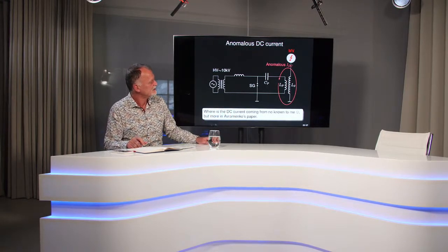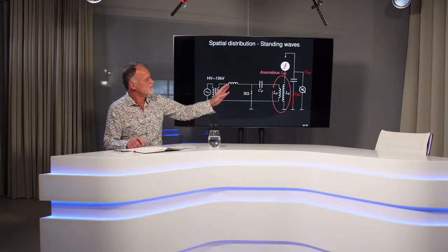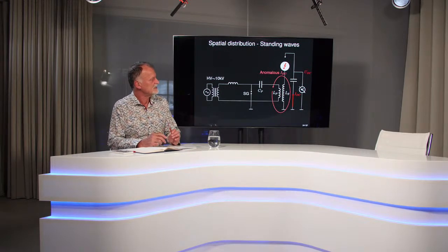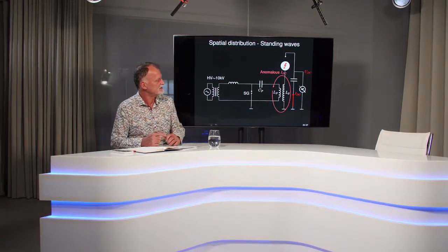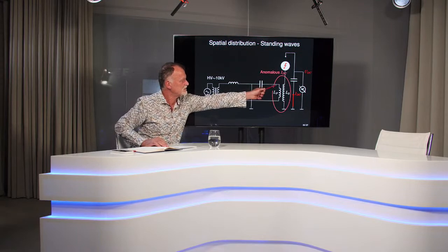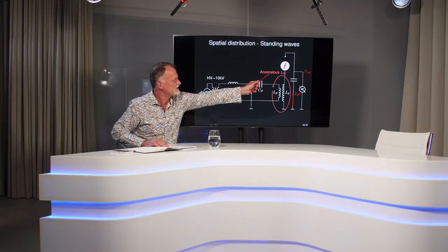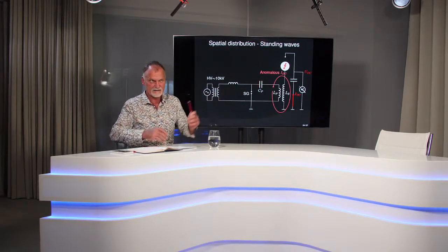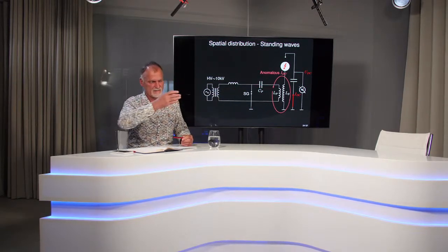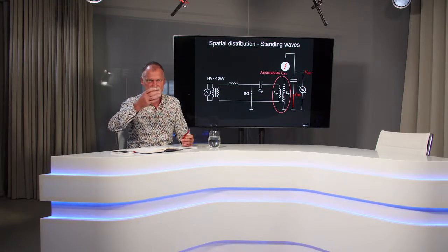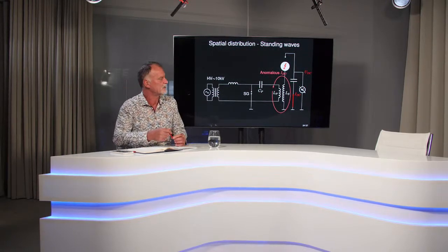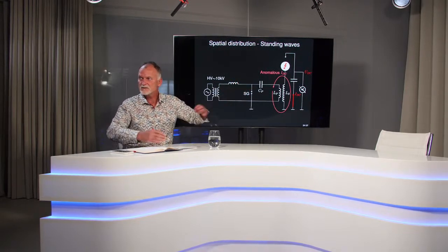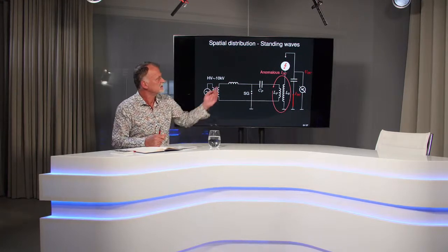If you go to the next slide, we can measure, and that's in my opinion extremely interesting, this DC current with this capacitive divider. We have a high voltage capacitor, and we measure the DC voltage generated on that capacitor. If the electromagnetic wave coming through the capacitor is a standard wave, oscillating around zero, then it cannot charge the capacitor to a DC potential, right? But it does.